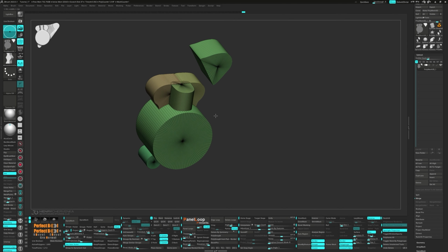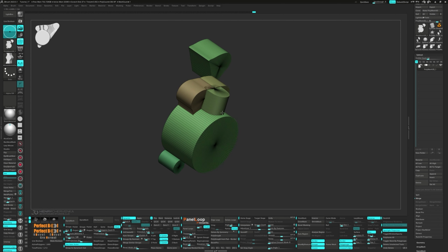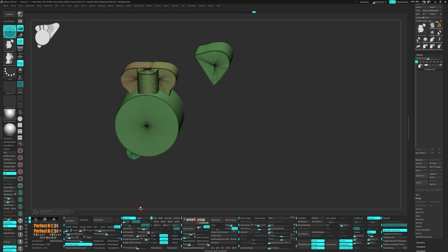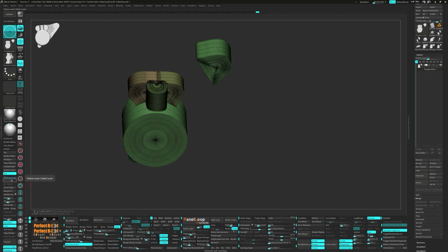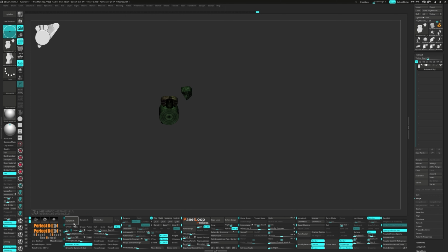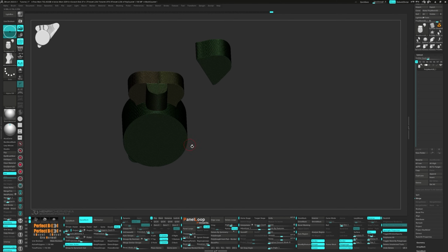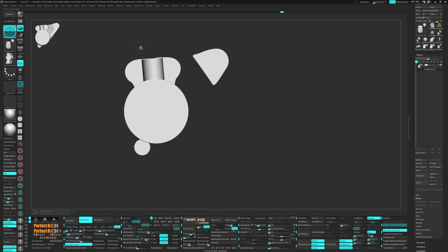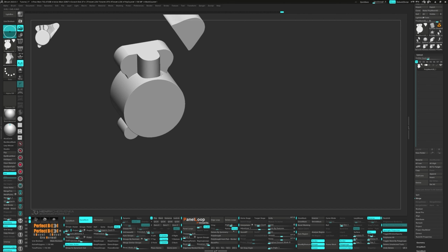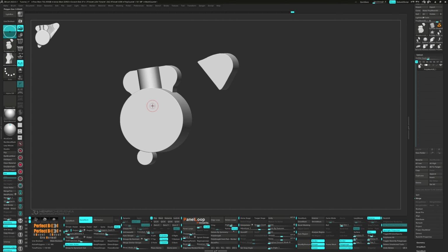Clear the mask and press QC50. Go ahead and set the smooth subdivision to 2 and hit Apply. Delete the lower subdivisions and set the Dynamesh utility poly count to 1. Now we need to grab the Clip Curve brush to flatten the top. Next, we want to use the picker to set the resolution and dynamesh it.